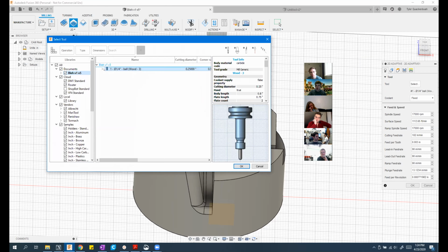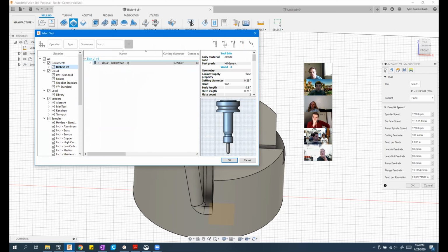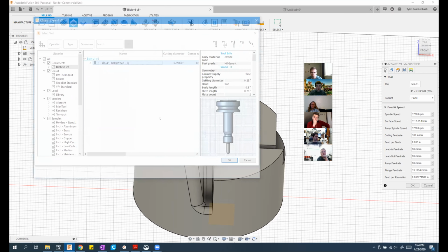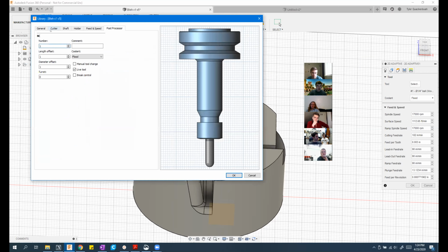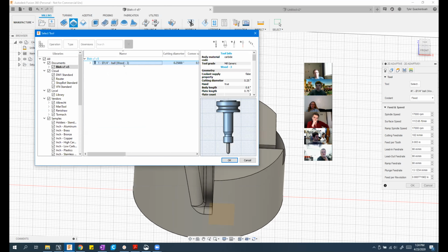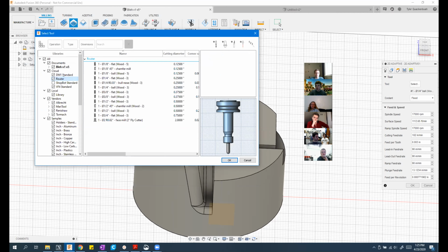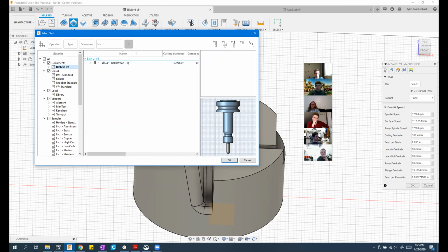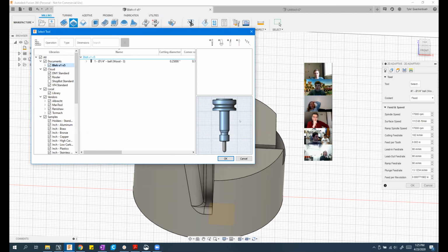There's a specific tool library associated with this CAM that I'm doing right now. If I edit this tool and go, ooh, I want to make that a 3 flute because I forgot I have a 3 flute ball and I want to use that instead, that does not update my cloud library. That edit only exists in this local library, if that makes sense.